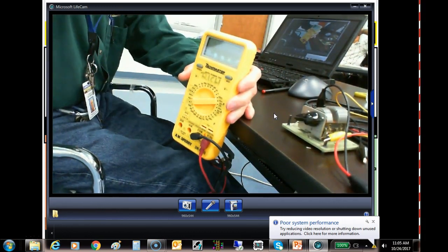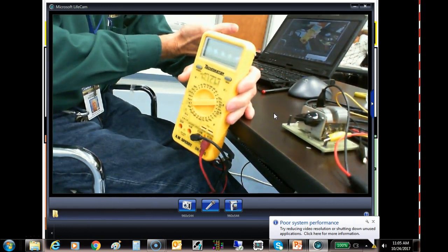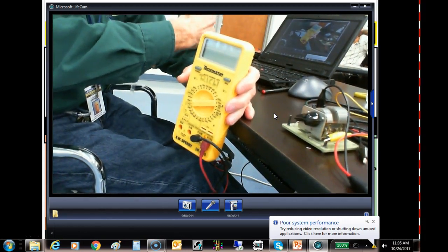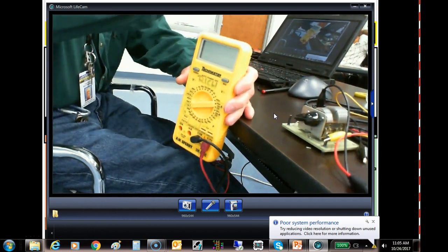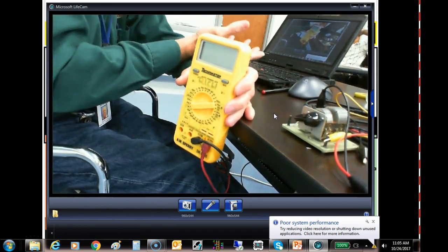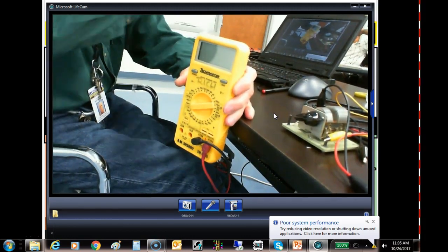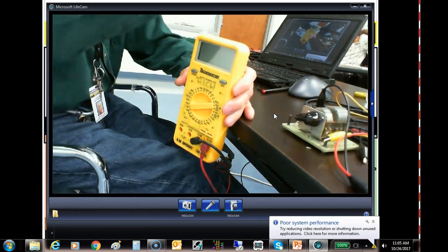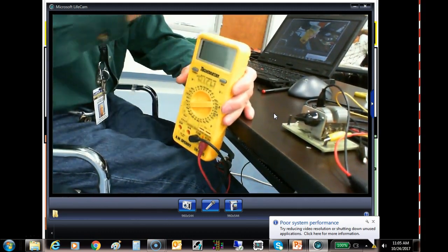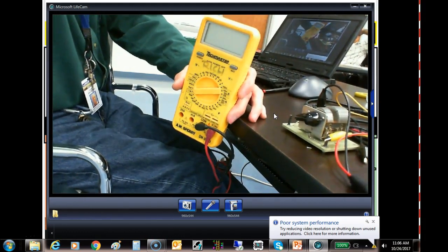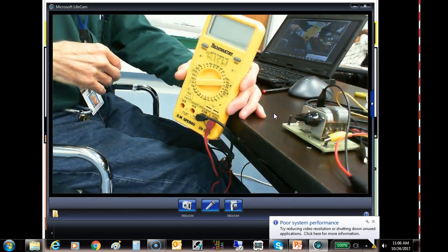But if you get a meter that's got a 2,000 volt range on it, and you put it into 1,000 volts, and you get an 800 volt spike, then that's not your fault. And we get spikes in industry all the time, just from them loading and unloading the lines. They run different lines all the time. You get spikes coming in there, and you might be using your meter in the right voltage, but if you get a high enough energy spike, the meter could still blow up.